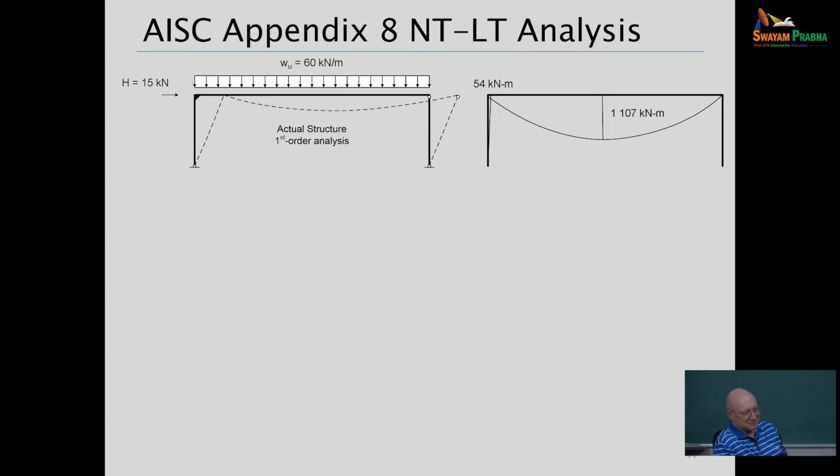So there is inequality in the boundary condition, and so when I take that as a pin joint at the right beam-column joint and then draw the bending moment diagram... If you take the horizontal load away, what would be the bending moment at the left-hand end of the beam?